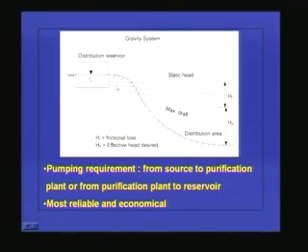And when it flows by gravity in the distribution system, you have a lot of energy loss. So, if you plot your energy grade line or the hydraulic grade line, it will be drooping. HF here shows the friction loss, and HE is the residual piezometric head at the tail end of the system, and this residual effective head should be more than what is desired.